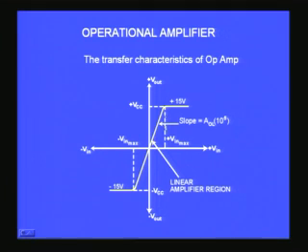So beyond that 150 microvolts, the output saturates at plus 15 volts. Whatever input voltage you apply, it cannot be multiplied by that 10 power 5, because if you multiply by 10 power 5 you get a much larger number, and such high voltages cannot be generated because the applied voltage itself is plus 15. Therefore it will saturate at plus 15. Similarly on the negative side, minus 15.